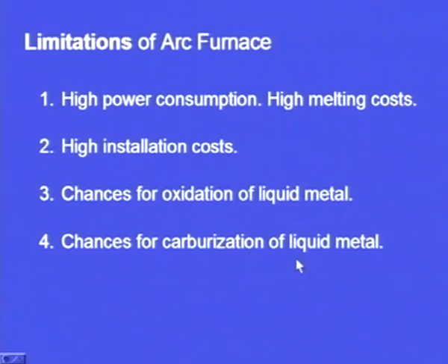Next one, chances of carburization in the liquid metal. Carburization means that carbon content increases. We are using graphite electrodes, these are consumed, and because of this the carbon content of the molten metal rises.